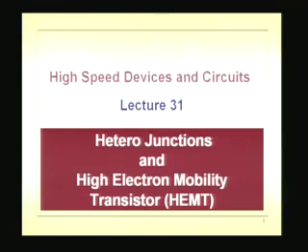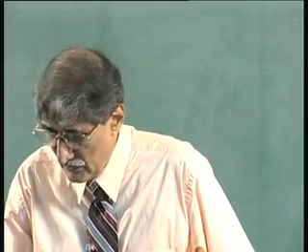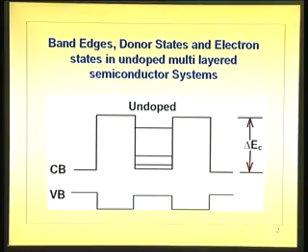So, last time we introduced the concept of heterojunction, heterostructure and heterojunction, and today we will continue on that. Few things related to the heterojunction I wanted to just point out. Here is a diagram which has a wide band gap material. See, this is the conduction band, that is the conduction band, and this is the valence band bottom.